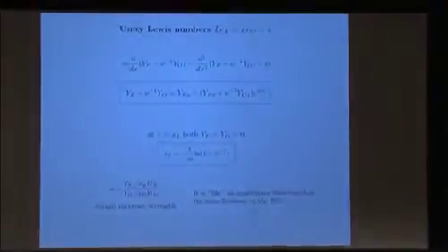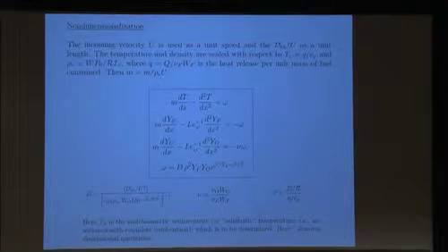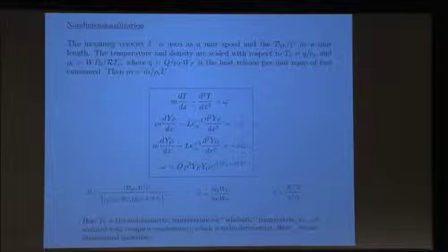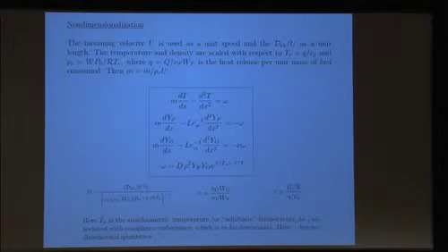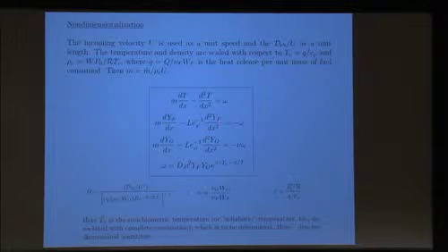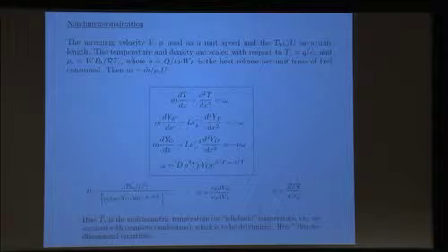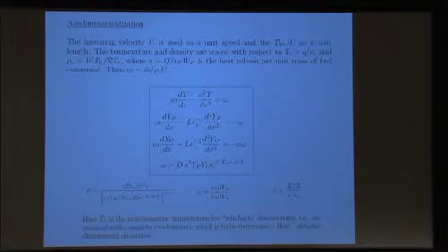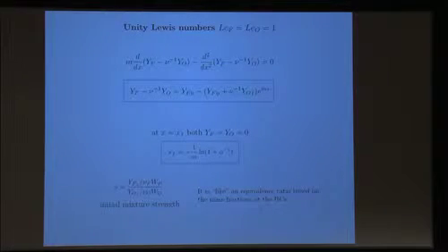One of the coupling functions is essentially the difference between the fuel and oxidizer mass fraction. Now here are the equations. Since the oxidizer equation has this stoichiometric coefficient, if you divide YO by nu, then the two equations have the same right-hand side. And if you subtract them, you get a reaction-free equation, or a conserved scalar. YF minus nu YO will be a conserved scalar. So here it is.